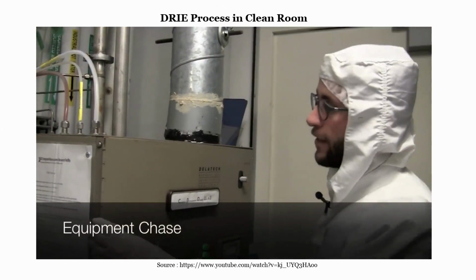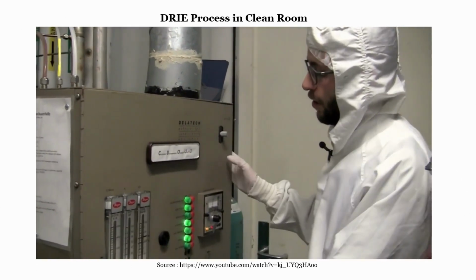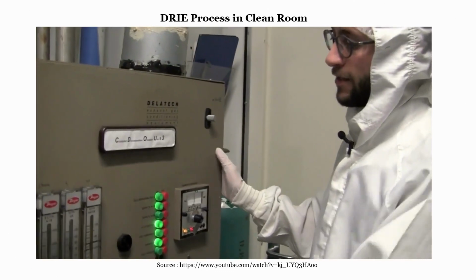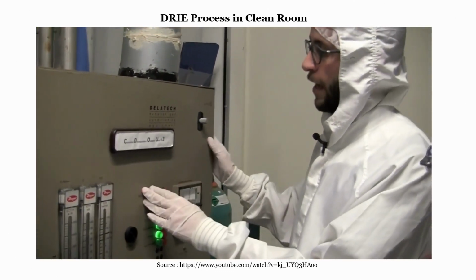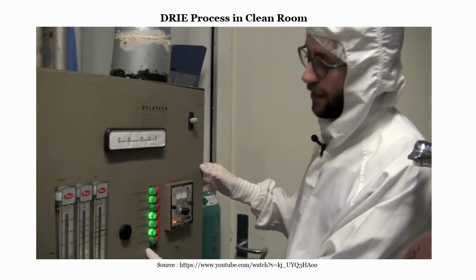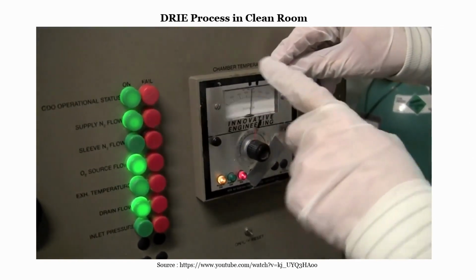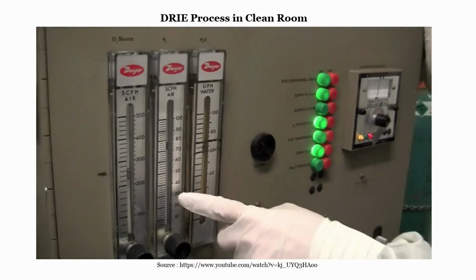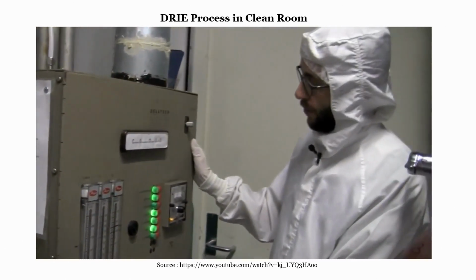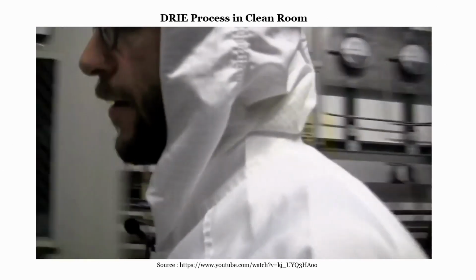The first thing to check in the gas chase is the CDO box. The CDO box is responsible for neutralizing the exhaust gases from the STS. By burning them, it makes them harmless. The thing that we have to check is that all the lights are green, and the temperature is within parameters, as well as the levels of the water, nitrogen, and oxygen. Once we check that everything is under working conditions, we will check if the operating gases are flowing.